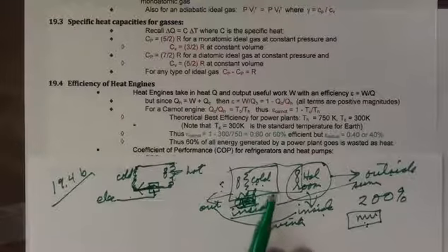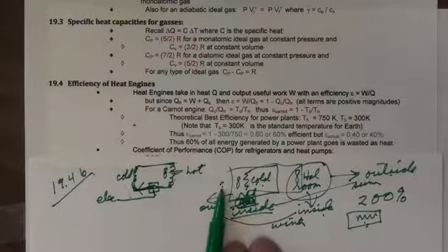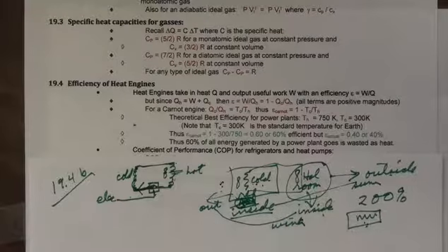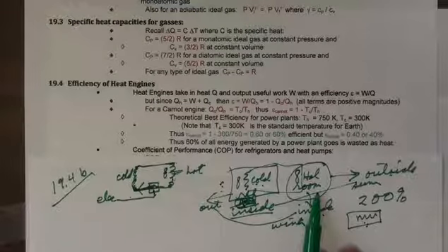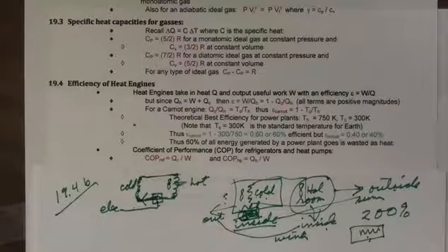But when you go up into the north and you get really cold up in Michigan, this heat pump is not going to be very efficient because it's so cold outside, it's almost as cold as this, so you're not pumping much heat in the reverse direction. Therefore, the heat pump is not effective there, and you have to use gas or some other means to heat the house. And even in South Carolina, in many places, if natural gas is available, it's more cost effective to use natural gas than a reversed heat pump. Of course, natural gas isn't available everywhere, so you have to use that.